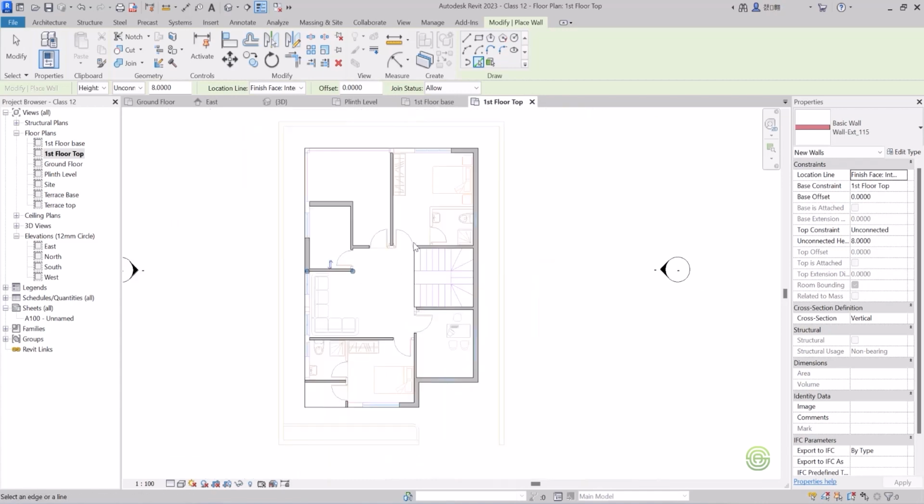But if you just want to do exterior modeling, if you are just focusing on exterior modeling, then we don't need to add these interior walls. We can just add the outer walls alone. If we also want an interior model, then we have to do this if we are going to take interior views as well. So anyways, in Revit, we have to do all the walls. It's not like SketchUp or 3ds Max, because in 3ds Max, if you're just focusing on exterior, you can just create exterior walls and take an exterior shot.